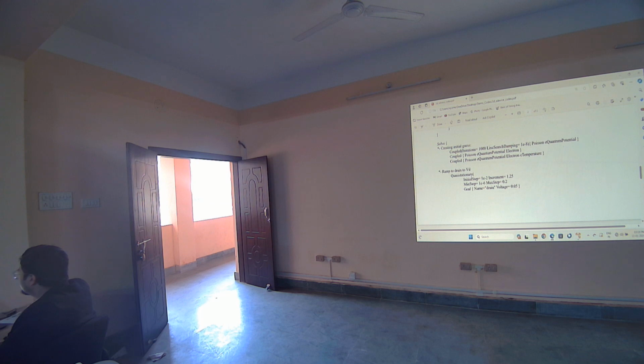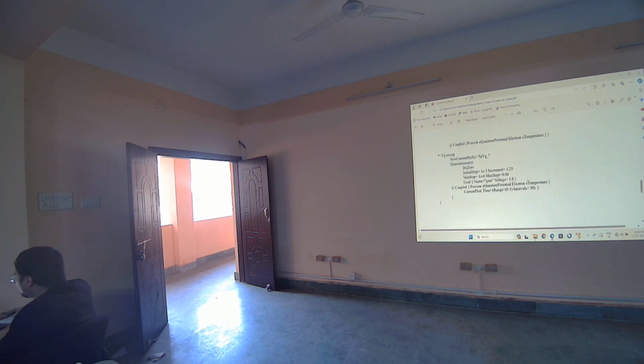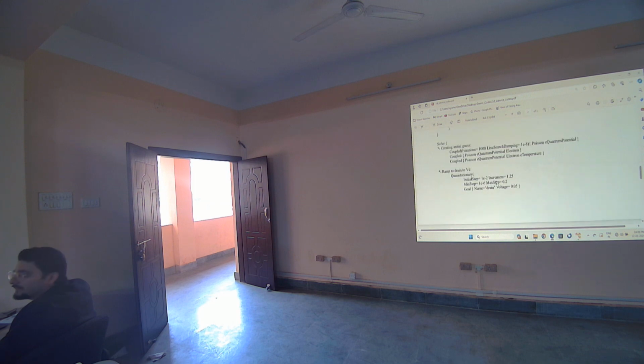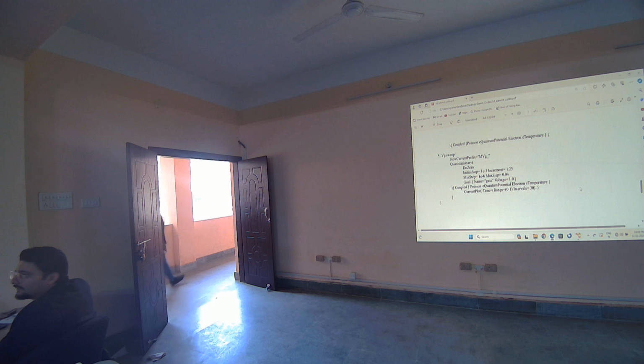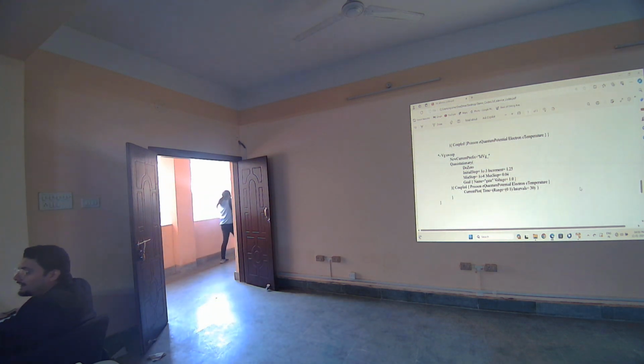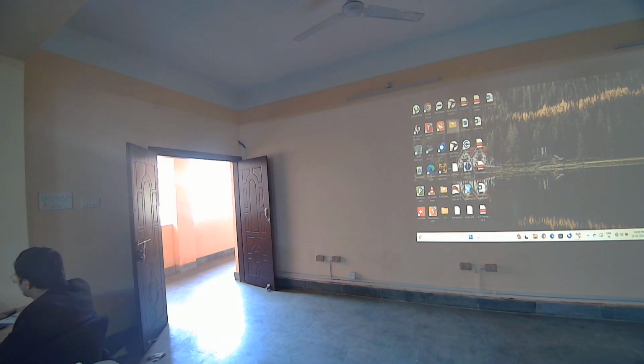Right? So this is how they have created an initial guess, and then they are providing the final ramp. Basically, they are providing the input signal so that they can plot a graph ultimately as an output, right? Because ultimately our motive is to get the ID-VG curve, right? So this is the VT sweep. Accordingly, they have ramped the VT, right? So ultimately, they are providing the input signals to the device, and accordingly, it will produce the ID-VG curve for us. So now that device is also over.